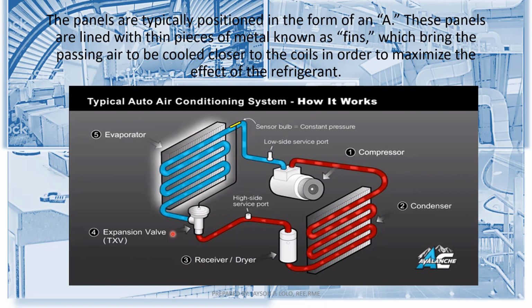The liquid refrigerant leaving the expansion valve is quite cold, which allows it to absorb heat from the air. The expansion valve also controls exactly how much refrigerant flows to the evaporator. More advanced expansion valves, such as thermostatic expansion valves, or TXVs, can automatically control the flow to improve the system's overall energy efficiency.